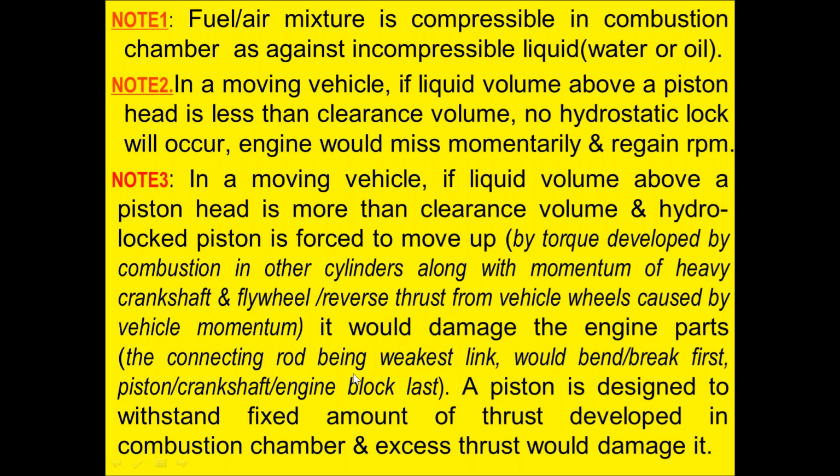It would damage the engine parts. The connecting rod, being the weakest link, would bend first and break afterwards. Then piston, crankshaft, and engine block are damaged last. A piston is designed to withstand a fixed amount of thrust developed in the combustion chamber, and excess thrust would damage it.